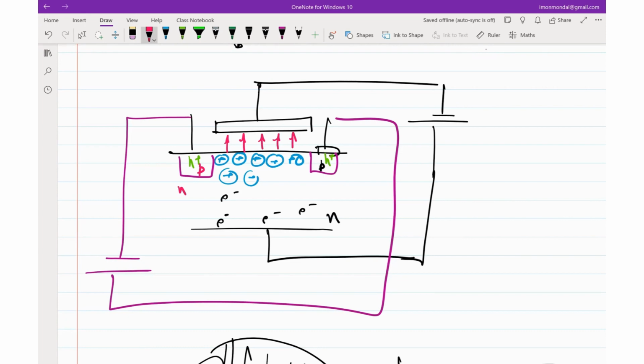If a PN junction is forward biased, it is going to allow a lot of current. If it's reverse biased, it's not going to allow any current. Right? So let's make an assumption that the battery voltages have been adjusted in such a way that this PN junction is reverse biased. Again, that is in our control because we can control the battery voltages, right?